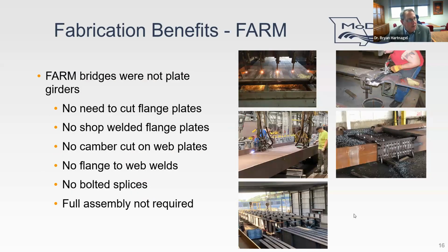But farm bridges, they were not plate girders. They were all rolled shapes, as I already showed. So there's no need to cut the flanges. So you don't have to do this operation in the top left. You don't have to shop weld flange plates. And so that's a top right picture here, doing a complete joint penetration weld, and then you've got to do non-destructive testing on that and all kinds of things.